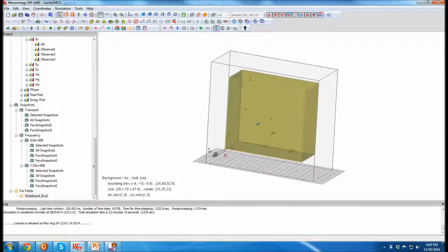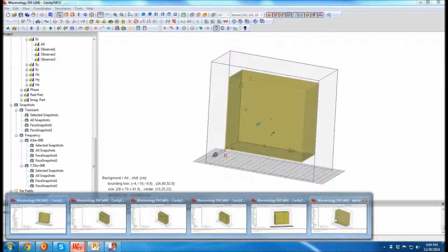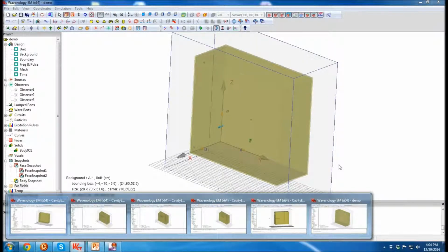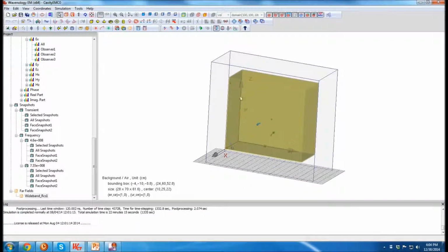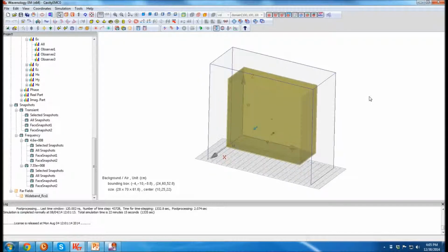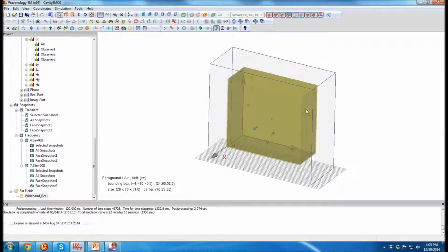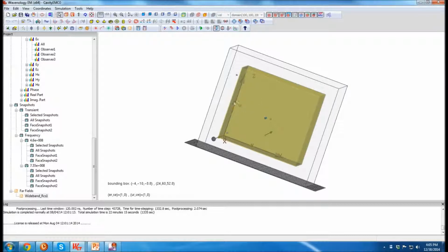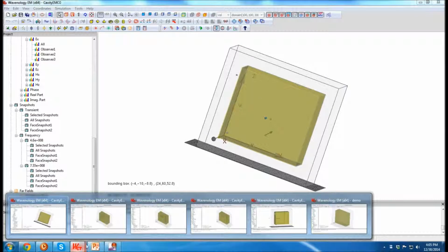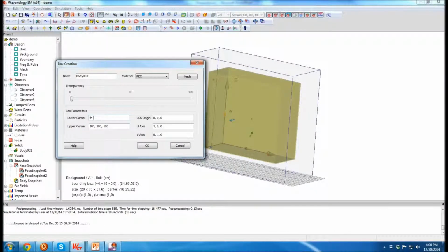Now, before we check out the radiation and EMC issue, the second thing we want to study is, if we change the internal structure. This is very typical if you have a motherboard, graphic card, also some mechanical metal frames within this box. What is going to change the property of these resonances? Okay, so let's first build a metal board right around here, and see how it changes things. So the position here we use is TH20, and here is 10, 20, and 20.5.